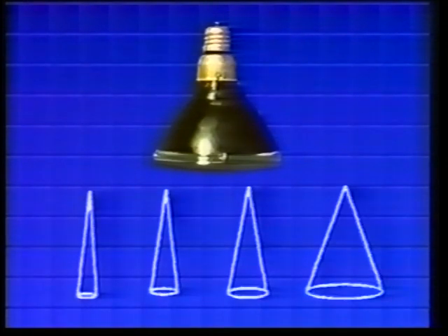By far the most useful directional incandescent light source of all is the PAR. A PAR is made from two pieces of glass, the reflector and the front lens. The reflector is a parabola which has the filament at its focal point. The reflector focuses light directly toward the lens. Lenses are available in a variety of patterns to provide different beam angles, varying from 10 to over 40 degrees.